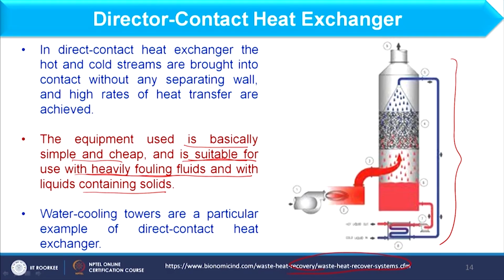So here hot gas enters into this, and it exchanges heat with the cold water which is coming from the top, or cold liquid. Subsequently the cold liquid is heated up and the hot gas is cooled down and exits from the top.